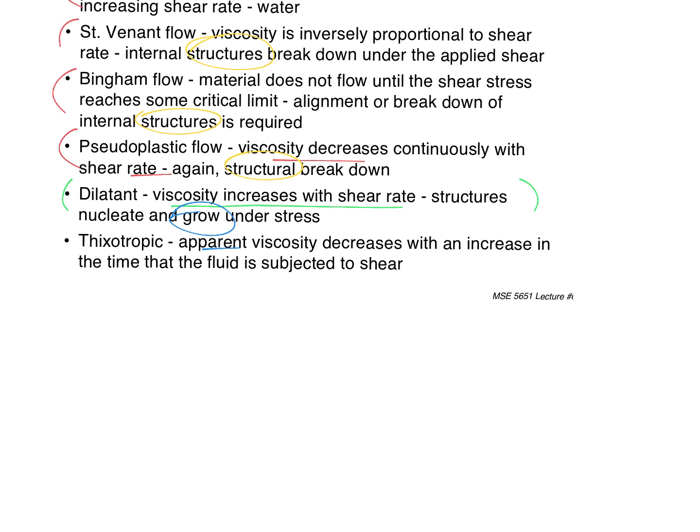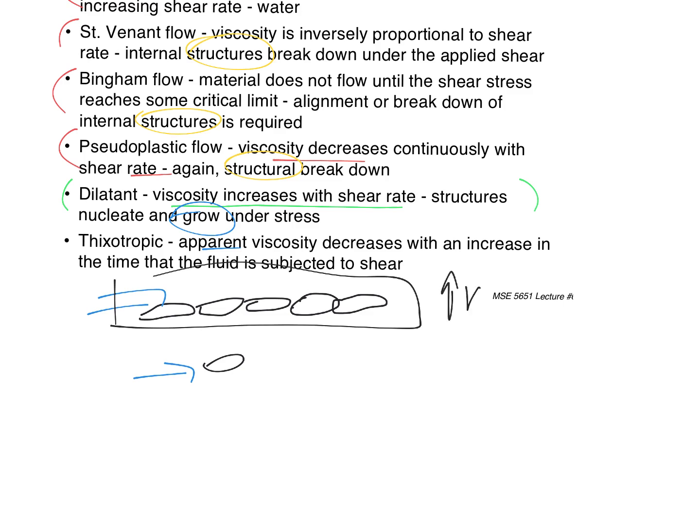And so the kind of structures I'm talking about consist of, let's say we have alumina particles, and this should make some intuitive sense. If those alumina particles all line up and form a string inside this, all right? So versus one individual particle by itself, it's going to be harder to make that string move versus a single particle, because that string has greater mass. You've got these forces holding these particles together, some of which we talked about. And so what this can then do is increase that viscosity versus a single particle by itself. Okay, so hopefully that makes sense.